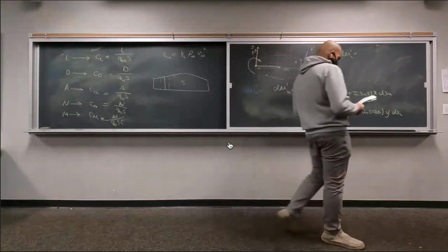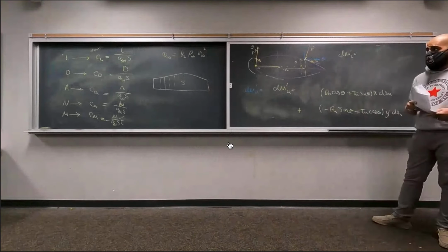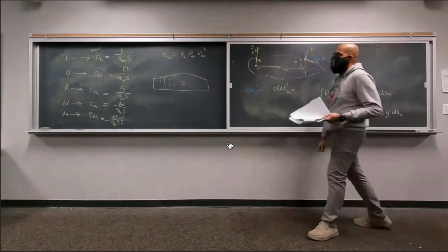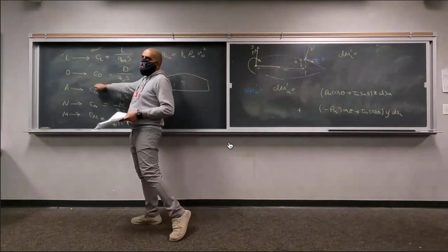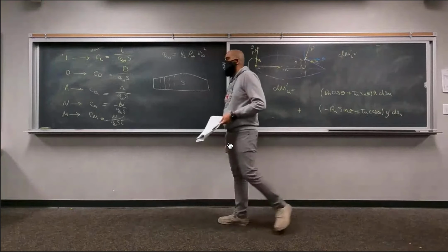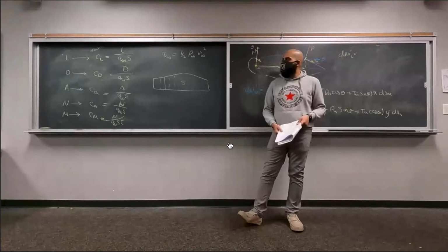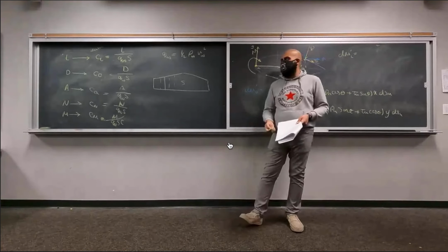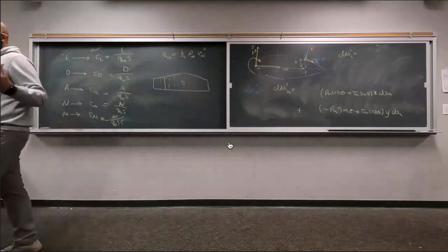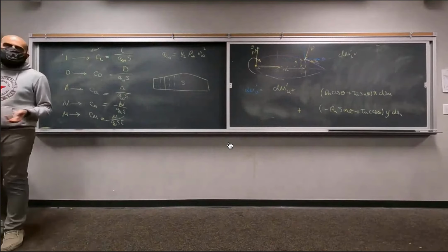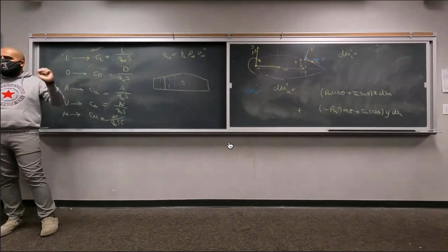Okay, so these are the main non-dimensional quantities that we are going to deal with in aerodynamics in general. In future chapters, your job is going to be to find C_L and sometimes C_D, but mostly we are going to focus on the lift coefficient. I don't want to say it's the most important thing in aerodynamic design and calculation, but it's usually the focus, right? If you want to compare two different wings to each other, you have to have the lift coefficient first and then the drag coefficient, right? And how it performs under different angles of attack.